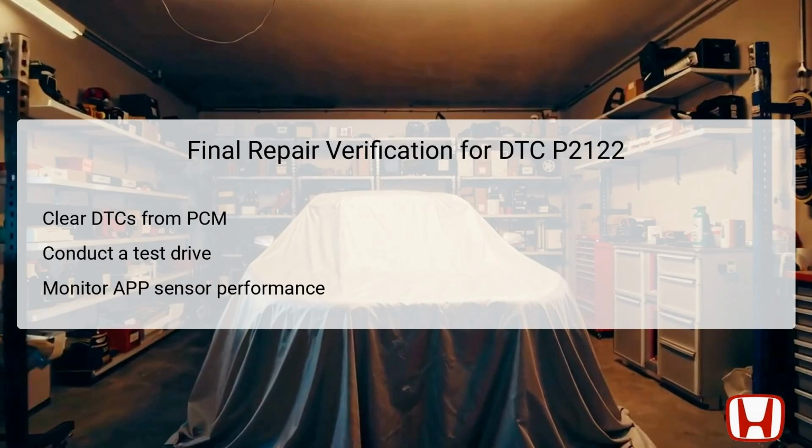During the test drive, pay close attention to the accelerator pedal's behavior to ensure it functions smoothly without lag or hesitation. Post-drive, use the HDS again to monitor the APP sensor values and confirm that they remain within normal parameters. Successful completion of this verification means the DTC has been resolved and the issue does not recur.